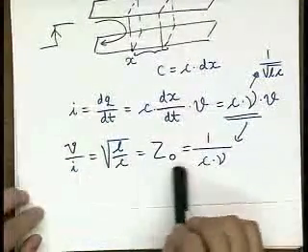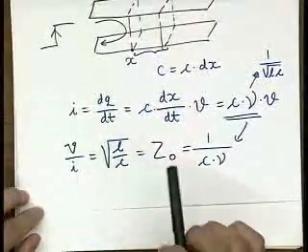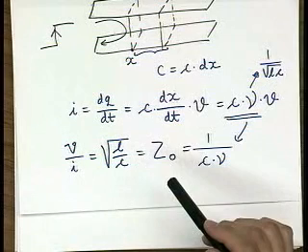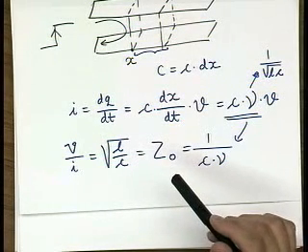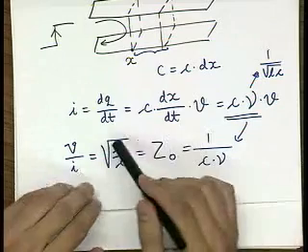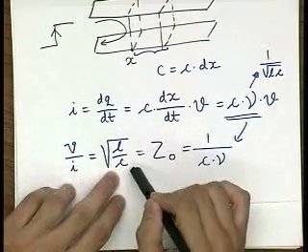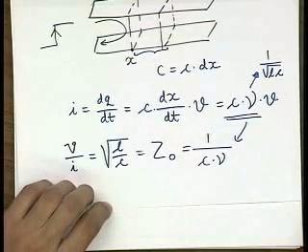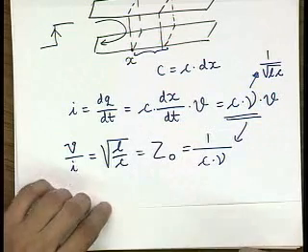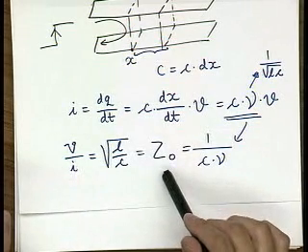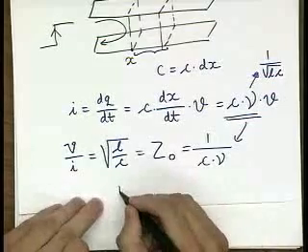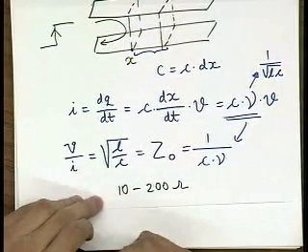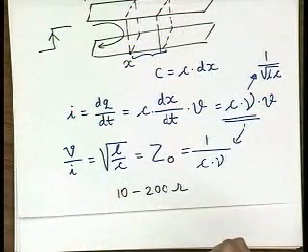And this impedance over here, as you see from this expression, is a function of the dielectric medium and the geometry of the wire and also the isolator around the wire, the dielectric that we said were lumped into these LC parameters, because we had different wire geometries and we wanted to make LC equal to epsilon times mu. And Z0 is not a function of the length or the frequency. Typical values are 10 to 200 ohms. And this is a constant real impedance.